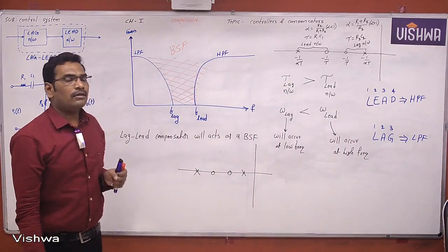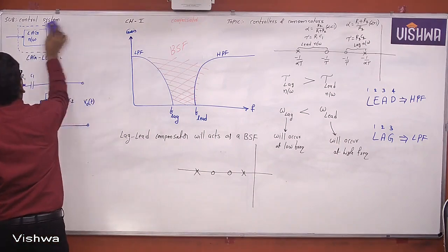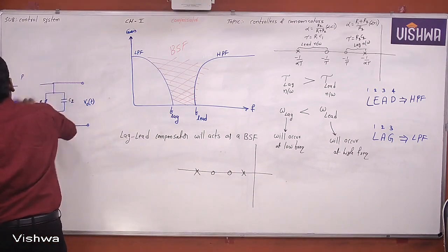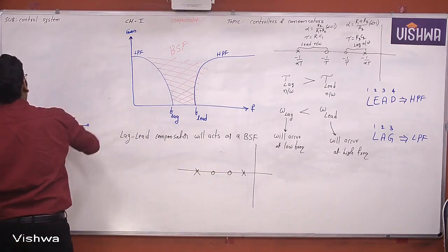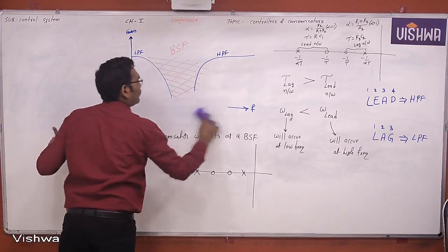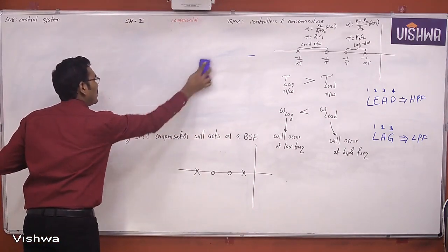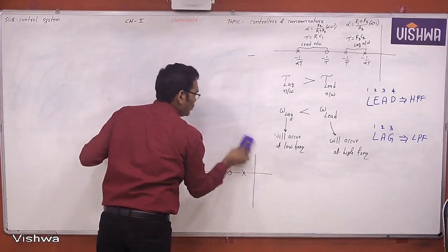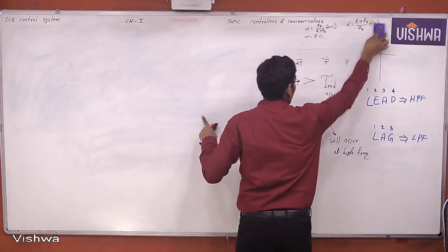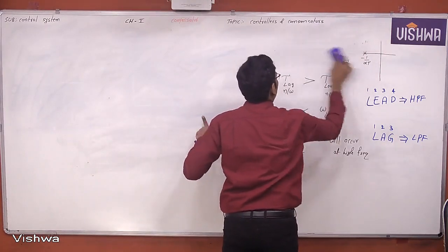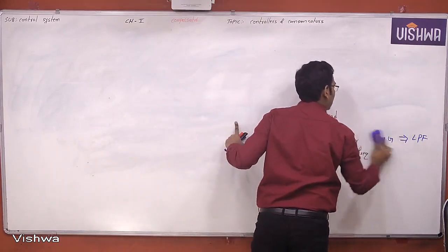Okay. Now these are the compensators and the combinations of the compensators. Not only that, also observe what should be the pole zero sequence in any filter. If any electrical circuit is given, first simplify those circuits, locate the poles and zeros on S-plane, and based on the location of poles and zeros, you decide which type of filter it is.